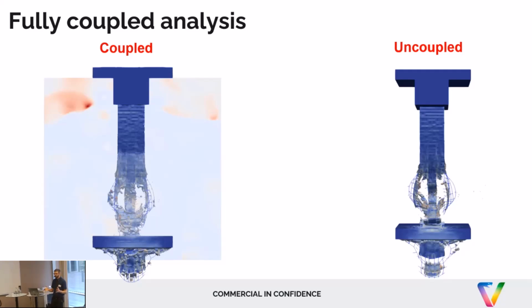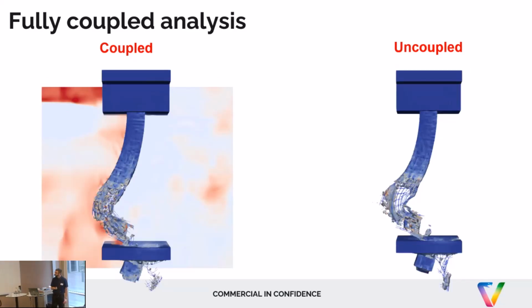They can move around where fluid elements used to be. So it does mitigate a little bit of the damage. And we can also see in both cases the deformation of the rebar. So even though VIPER itself does not model or really care about the rebar, because it is fully integrated into the OpenRadioss model, it does get the deformation as you would expect. And in both cases, the deformation of the rebar follows along with the full destruction of the column as you would expect. And some of the differences can be a little bit more visible on the side-on model, where again, we definitely see some more damage on the uncoupled model.